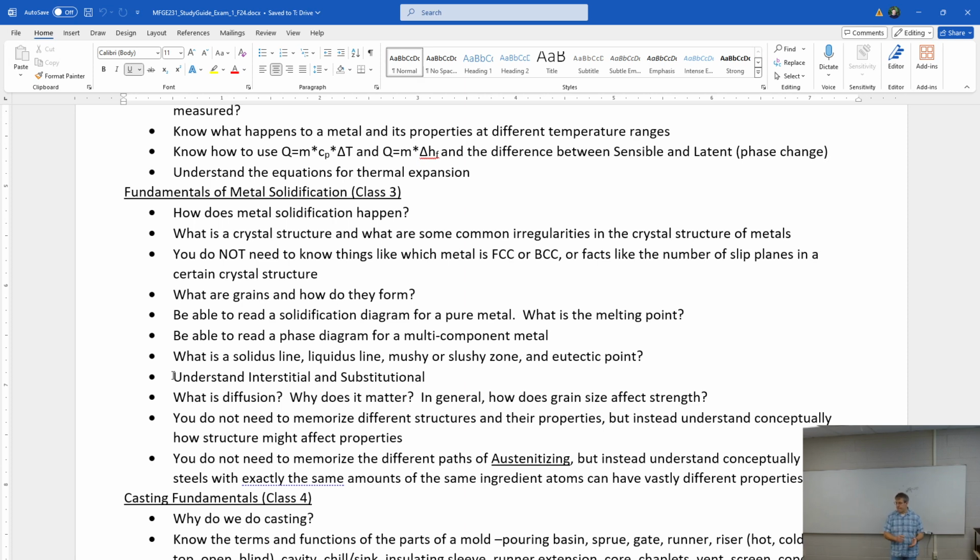And when you quench it too fast, will it get brittle? Well, when you quench it at all, it gets brittle. But you can control the rate at which it quenches, and that will control the amount of diffusion of the interstitials that can continue on as it is cooling. And it helps you to set the ductility or the strength of the material. Thank you. Is that good? Yeah.